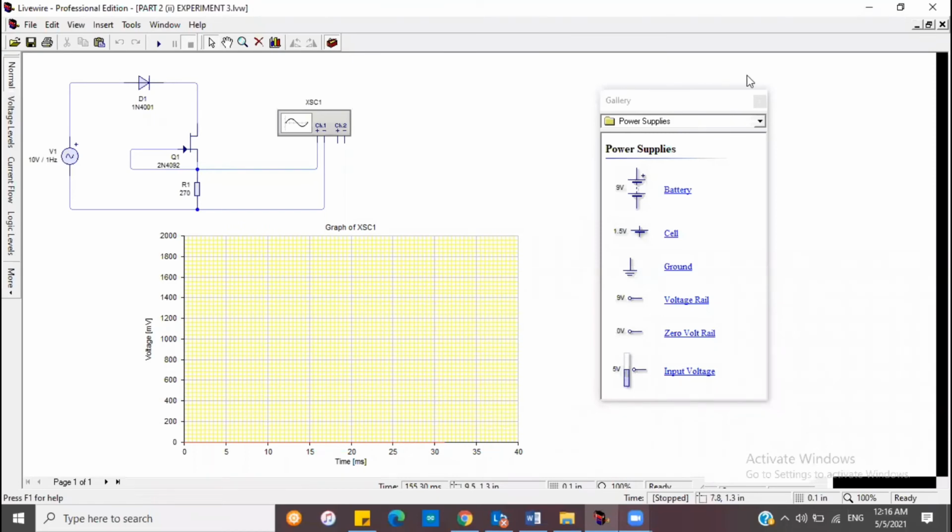So this is the FET curve tracer circuit. The components used here are a signal generator, resistor, diode, and also an oscilloscope. This oscilloscope was added to observe the characteristic of the curve. Basically, the curve tracer works by applying a swept voltage to the terminals that are being tested. So it will determine how much current can flow through the DUT at each voltage.